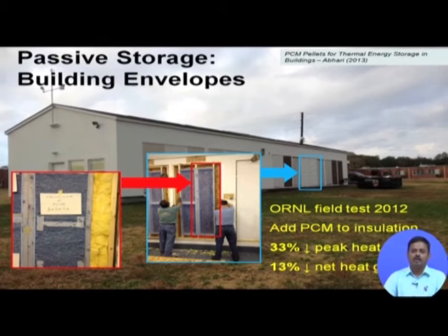Actually, it may be good, it may be more comfortable, all right. Or in a moderate climate where the days are hot and nights are pleasant, I can choose a phase change material whose melting point is somewhere in between the average day temperature and the average night temperature.